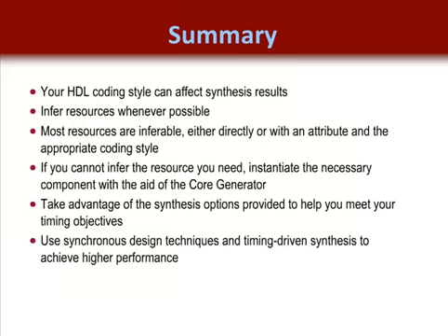And as you get to the newest and the latest, greatest resources, it becomes more likely that you'll have to instantiate. Take advantage of the synthesis options that are included with your tool, and be aware of the caveats associated with them. Use synchronous design techniques always to make sure your design runs reliably, but also use timing-driven synthesis to achieve higher performance. And that's probably the most powerful of the different synthesis options we've described.